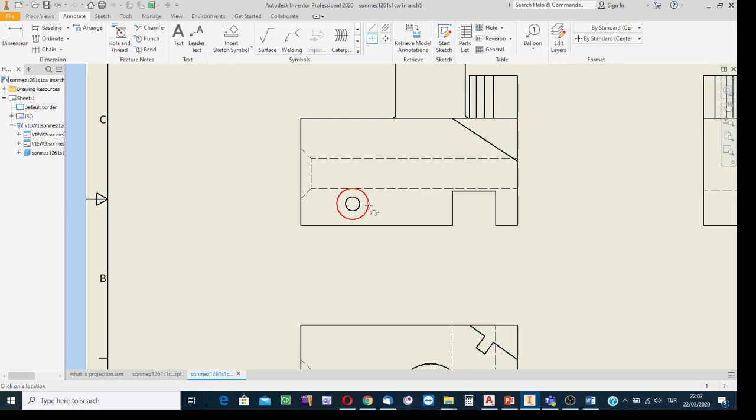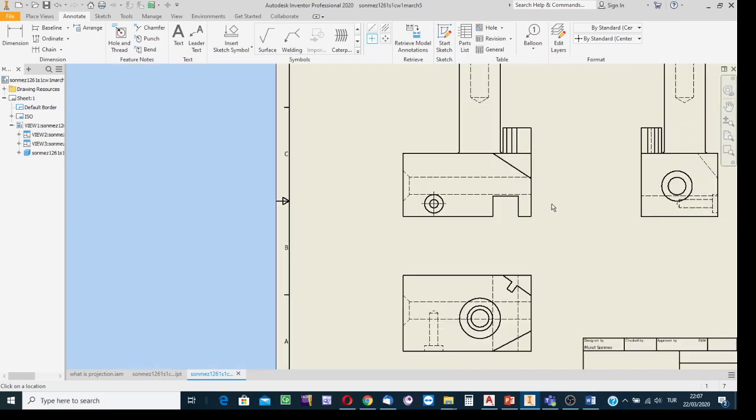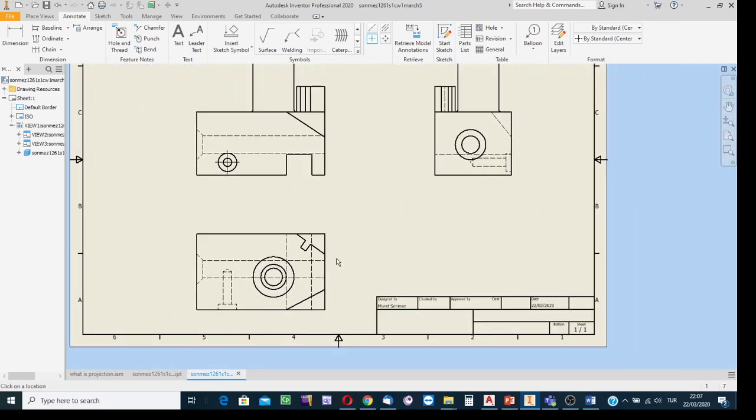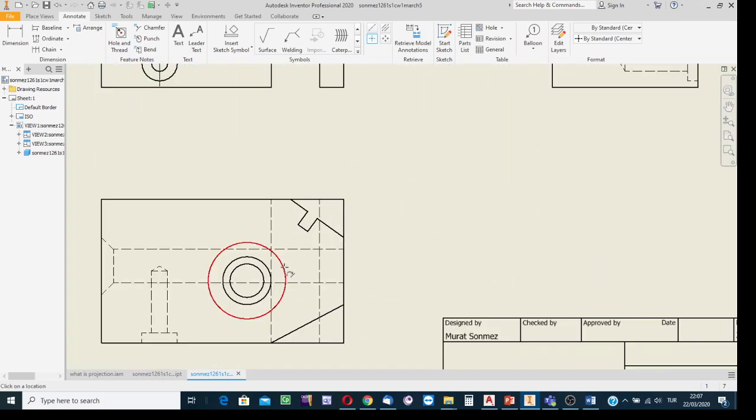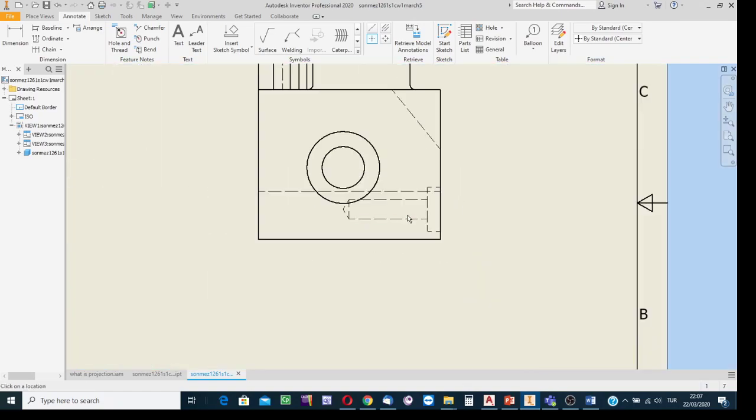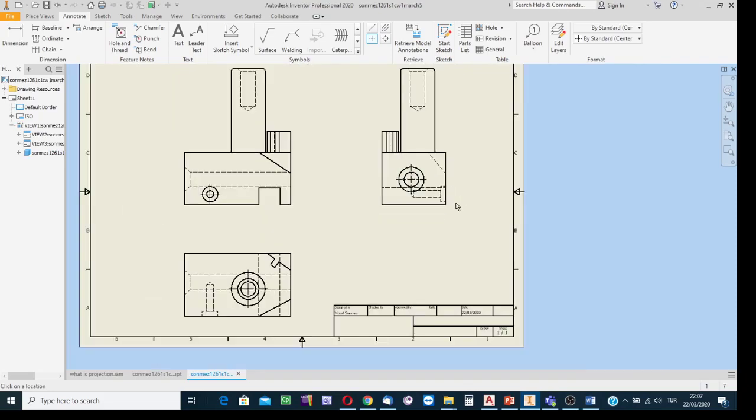We have two concentric circles. This is the image of one of the entities. Since it is a full circle, symmetry axes are needed. With a click, indicate. On the top view, similarly, there are some circles. Select the outmost one for having the axis of symmetries for all. On the left side view, this is a full circle; indicate it and have the horizontal vertical axis.